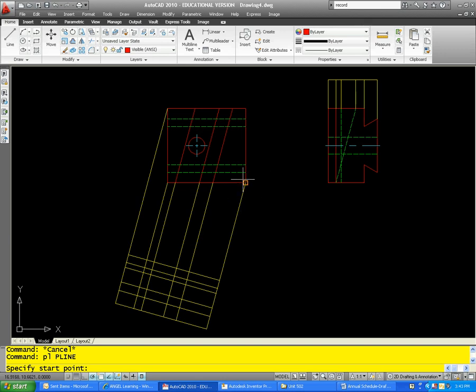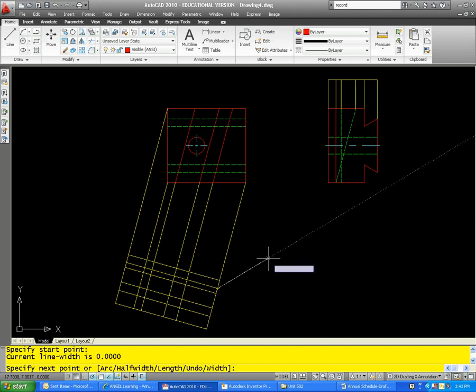Okay, and I'll look over to my drawing here, and I can see that, as we discussed earlier, this plane is on this elevation. Okay, which is the fifth line from the bottom, so 1, 2, 3, 4, 5. Okay, so that's where that point is, and it maintains that elevation until it gets to this point.